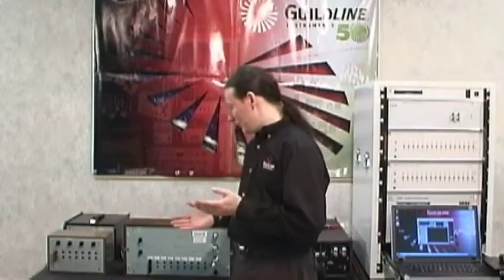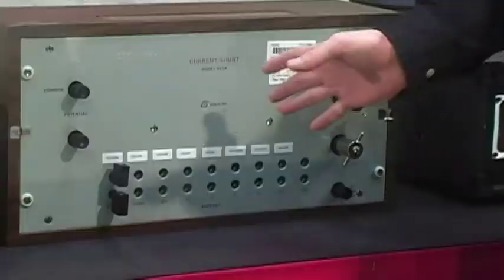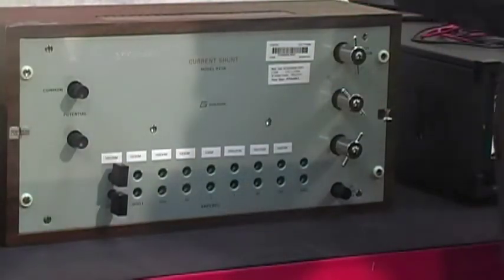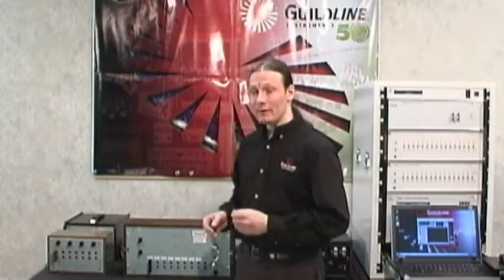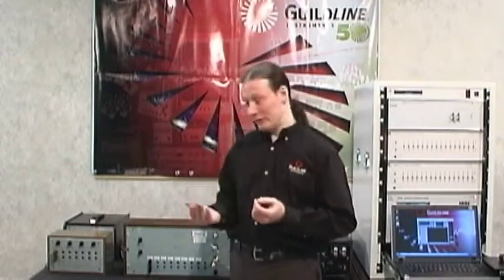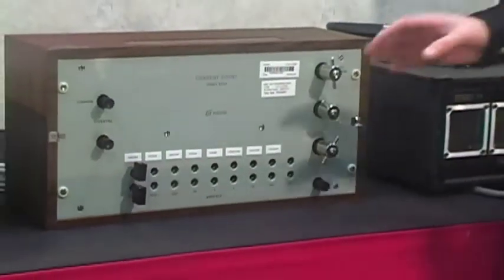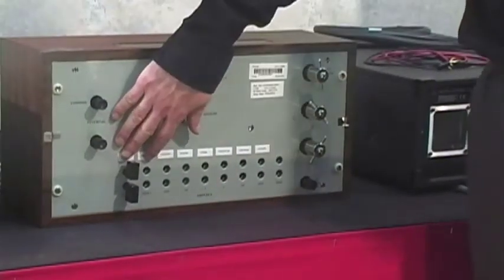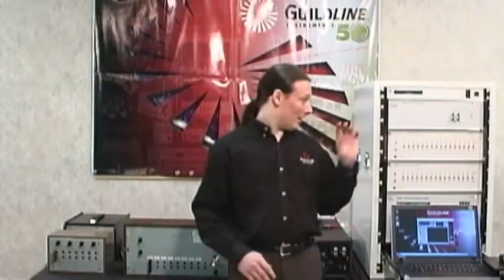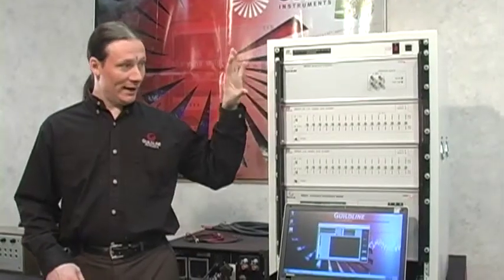In essence, it's still a resistor and it's a shunt, but it has several different values. And so to calibrate one of these shunts takes a lot of configuration and setup. The software utility is designed to basically get rid of all the manual setup processes and running multiple files inside Bridgeworks, where you hook it up, start the measurement, and it'll just prompt you every time you need to change the ranges, which will still have to be a manual process, simply because some of the measurements going all the way up to 10K, they will take a measurement just using the bridge